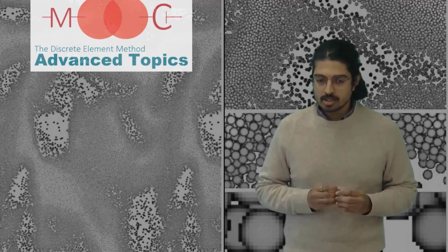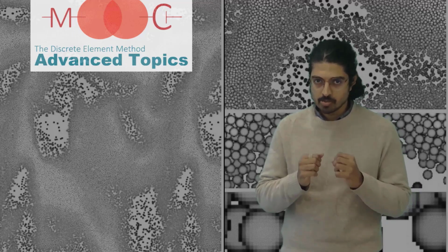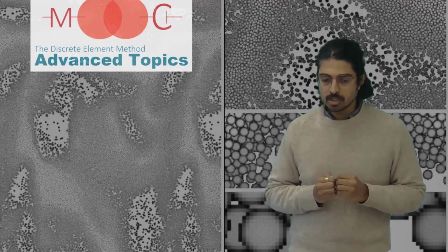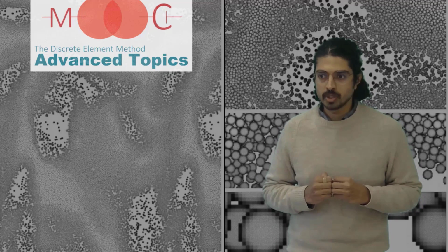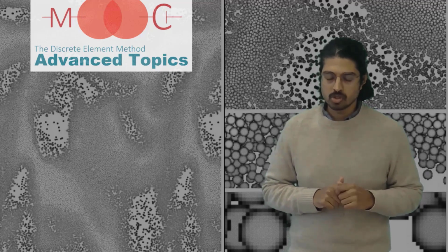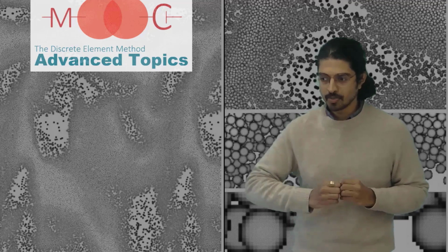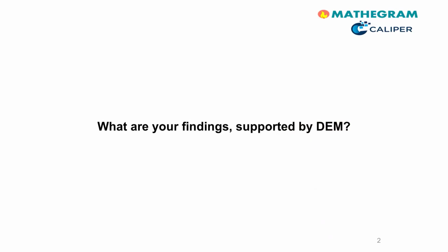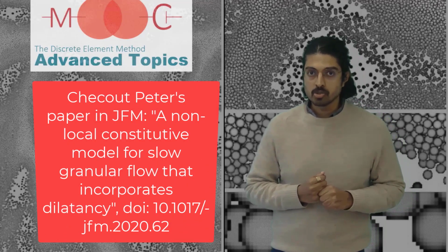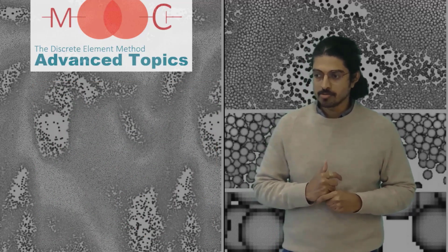In this particular case, the particles have a property known as dilatancy because powders, individual grains cannot be compressed beyond a point. If you want to shear material, these individual particles have to push each other out of the way. This creates this low density region in regions of shear, also known as dilatancy, a cool phenomena found by Reynolds of Reynolds number fame over 100 years ago. For powders, we found the presence of secondary flows even at very low inertial numbers, and that is a really cool concept that DEM helped us find.